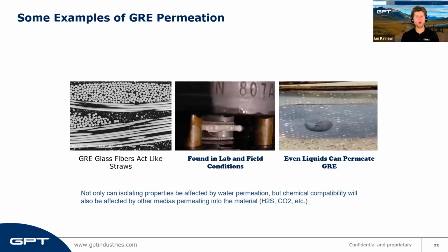And here's a picture of why this happens with GRE. It's made with millions of microscopic glass straws in an epoxy matrix. And in both conditions, we've seen that gas and media can actually permeate. They can force their way right through these cracks right here.